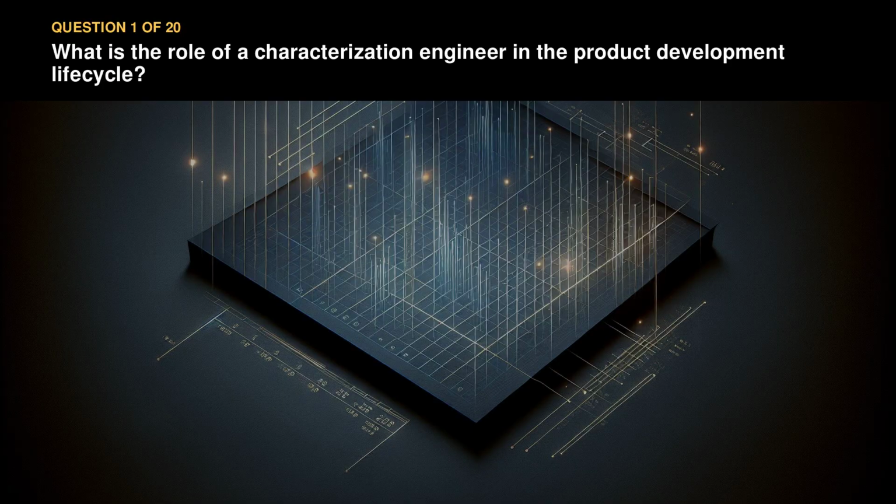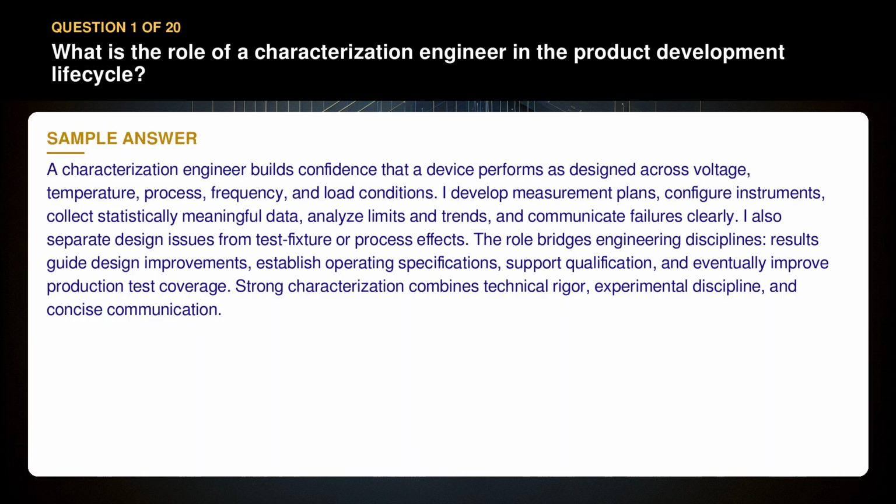Question 1. What is the role of a characterization engineer in the product development lifecycle? A characterization engineer builds confidence that a device performs as designed across voltage, temperature, process, frequency, and load conditions. I develop measurement plans, configure instruments, collect statistically meaningful data, analyze limits and trends, and communicate failures clearly. I also separate design issues from test fixture or process effects.